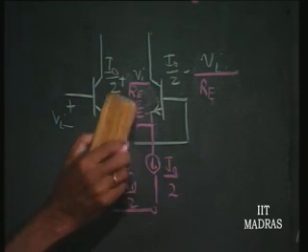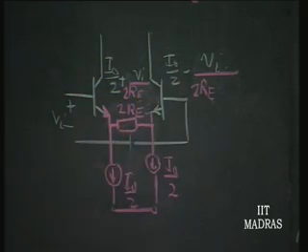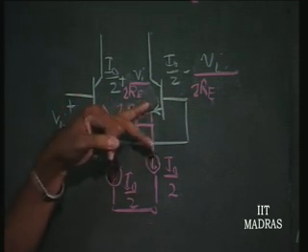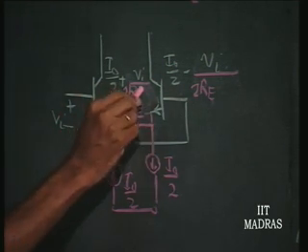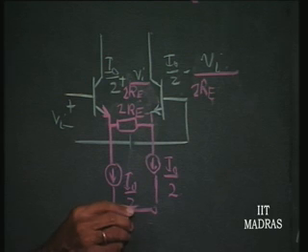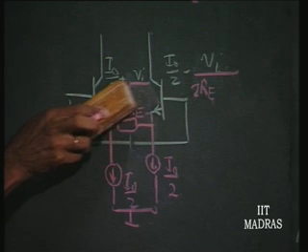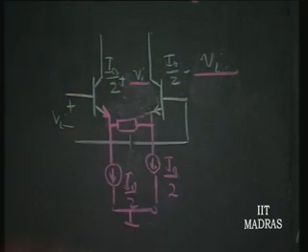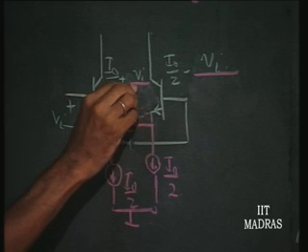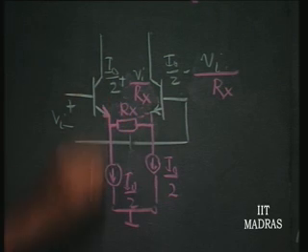Actually, the earlier thing should have been 2 R E, I am sorry. Right. V I by 2 R E plus 2 into 1 over Gm it was. So, you simply replace this by 2 R E, or actually speaking it is a single resistance, because there is nothing like 2 resistances separately here. Now, this is V I by, let us call it R x. Is this clear or not?